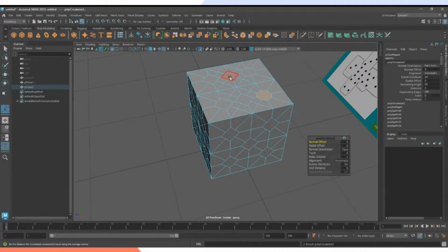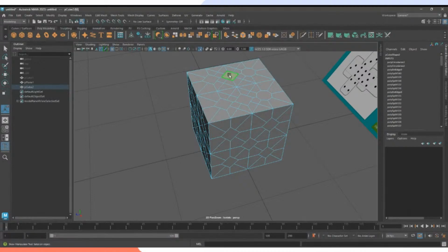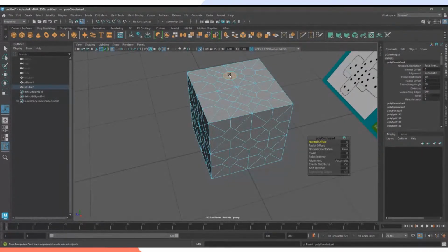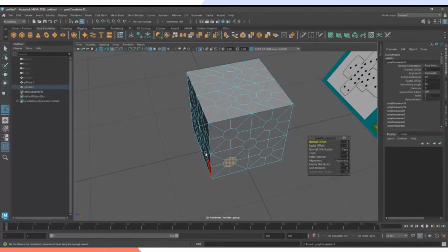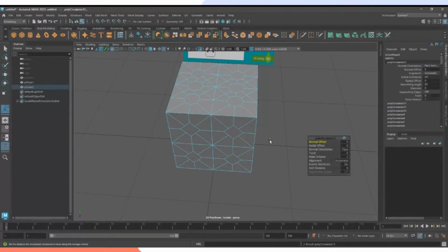So for example, I'm just gonna press select here, and then the repeat command is letter G. So press G on your keyboard. You can basically do this a lot faster now because you're just repeating the same command.